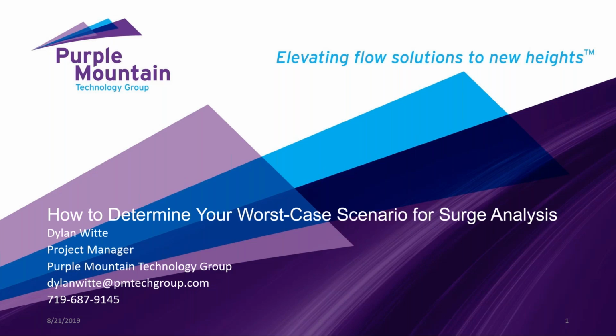And when you use AFT Impulse for the scenario manager and the graphing capabilities, it makes it a lot easier to really get a strong understanding of what's going on in your system. That way you can use it to help clearly explain to your operators why it's so important to close these valves in these ways, or why it's important that we have various surge suppression equipment in place, and why it's important that things are sized properly rather than just sticking things in the system and hoping it works.